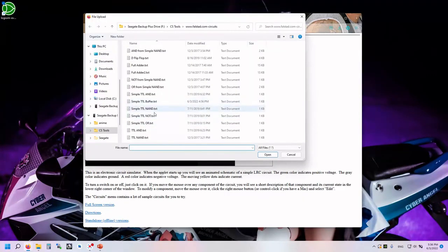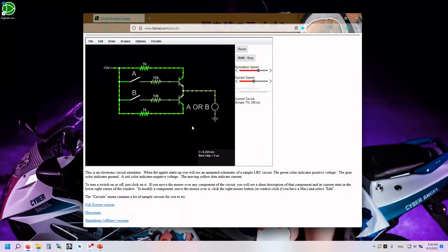And then the last one we're going to look at is the OR. And the OR looks a little bit like the NOT, and it works kind of the same way, except now we have our two transistor gates in parallel. Okay, so that if either one is on, it gives it a path through to that LED. And that's how that's working. Okay, without that, there is no path from the input to the LED. And so the LED does not light up.